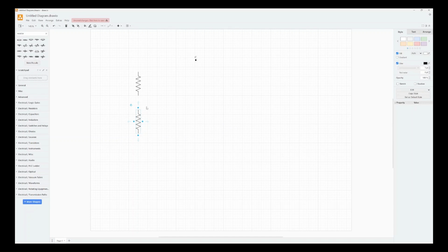You can see the lines hop up, and let's say I want to connect them together. Well, I can do that. I don't want to resize it. I get this arrow, and it drags it up and connects it. Now you notice I got an arrow out of the deal. Well, I don't want an arrow. So now I'm going to select this line segment that I just created, and I'm going to go over here to the right-hand side. And on one end of the arrow, the line start, there's no symbol on its end. This is the line end, and it's showing an arrow. So if I say no line end, now you notice that arrow went away.